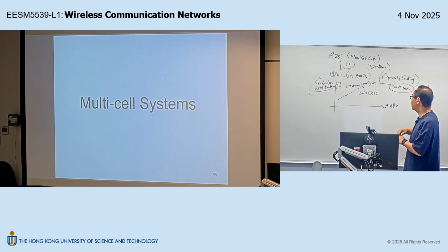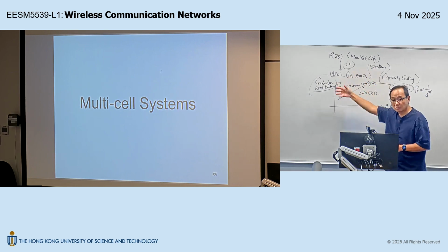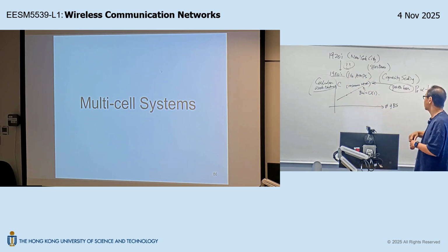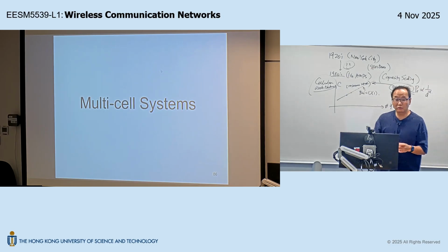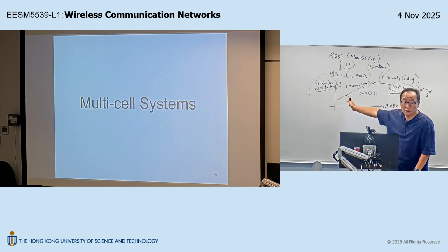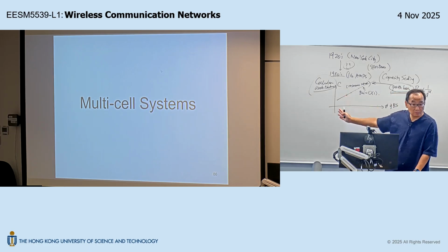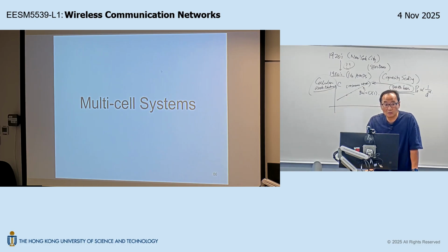So the fundamental reason why we have today's very affordable cellular network is because of path loss. Path loss is your very important friend. Without path loss, I can say even today, we won't have affordable mobile phone services, okay? And the cellular architecture is a very clever architecture that makes use of this path loss effect and turns this enemy into something helpful.